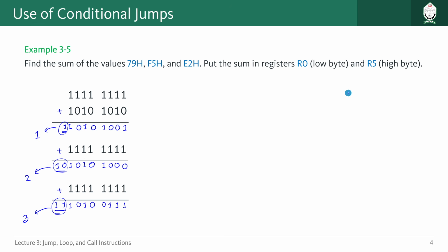You know that to save this data or result, we need at least 2 registers, because each of the registers has a maximum of 8 bits. So what we are going to do is take one of the 8-bit registers to save the lower 8 bits, like we have here in this portion. To do this, we are going to use one of the registers.